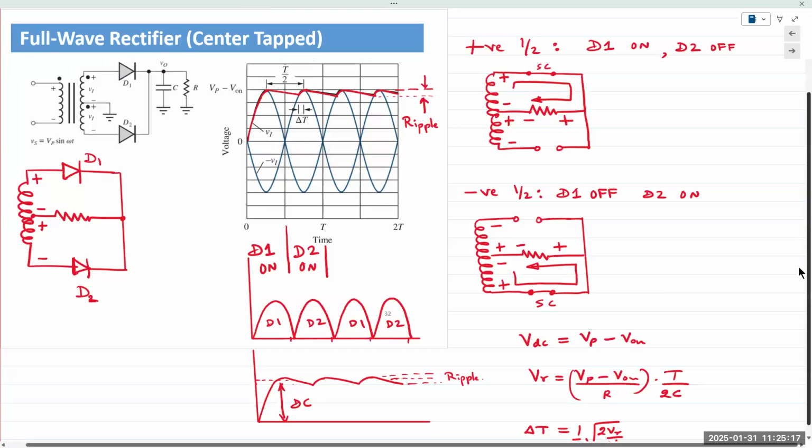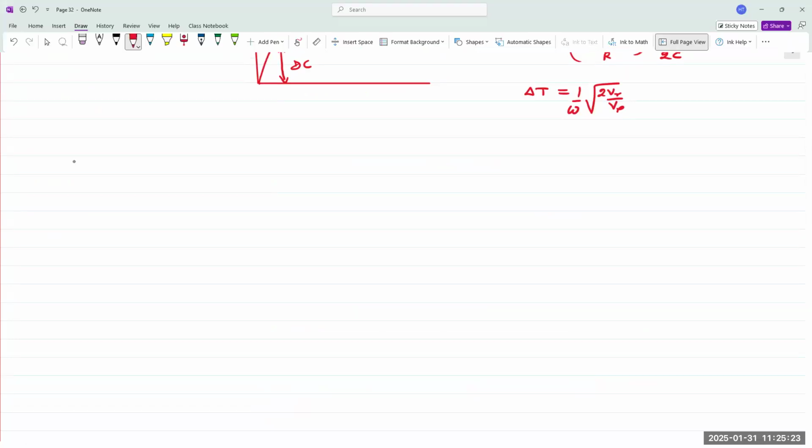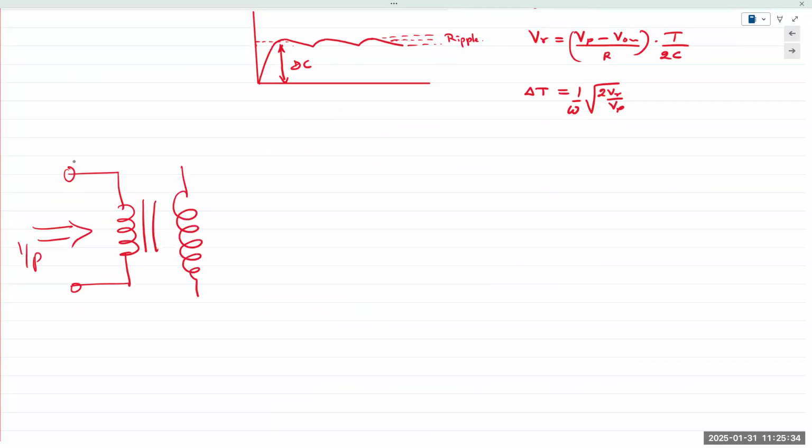So a center tap transformer is basically, this question being asked is about a center tap transformer. So you have a transformer. This is the primary side where the input's going in, and this is the secondary side, the output. A tap is basically a connection. You're poking into the secondary winding and taking out a connection. So if you make that connection directly in the center of the winding, the turns ratio is now divided.